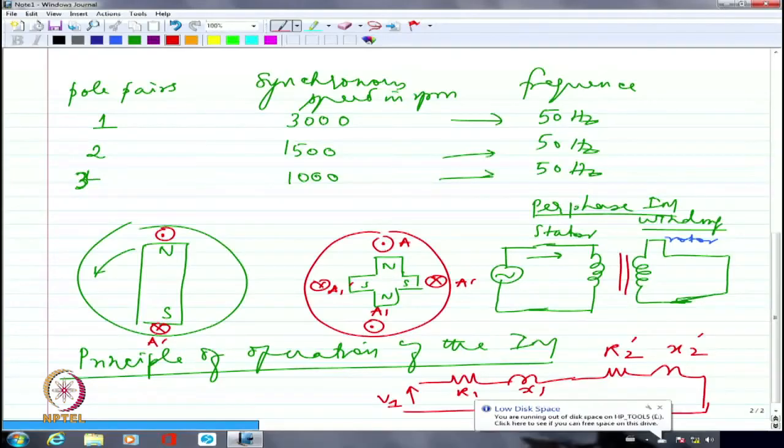So this will take place until a beautiful balance happens in such a way that the frictional torque or whatever is overcome. If I don't have any load on the rotor shaft, the frictional torque will be overcome with a small torque developed by a small current flowing, by a small induced EMF, which will come in handy if there is a small relative velocity.